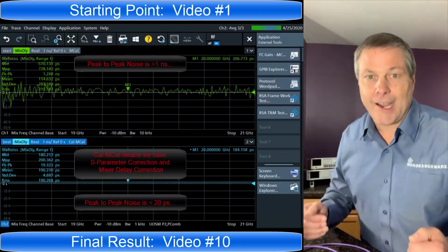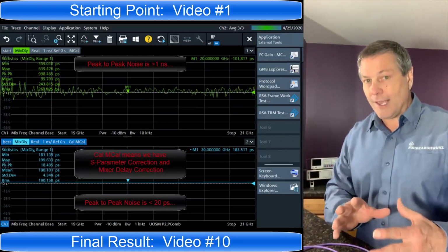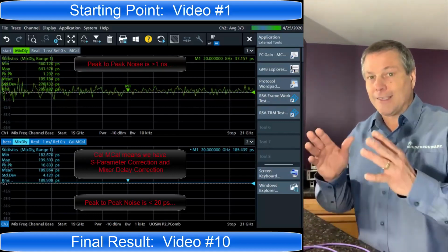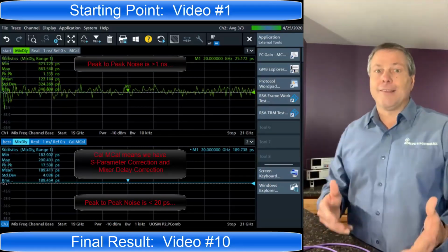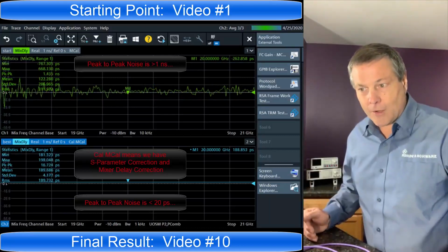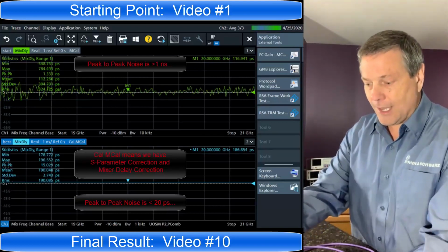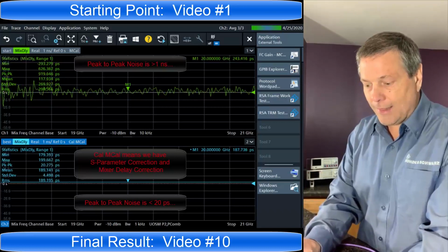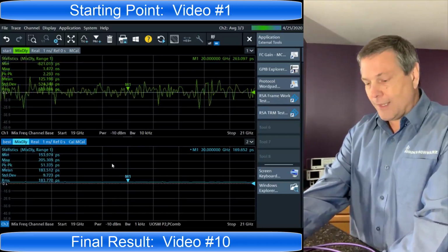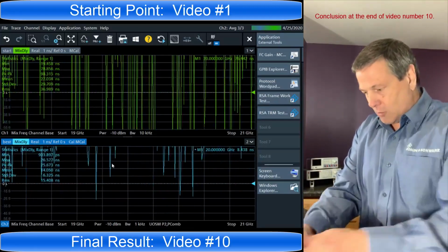This is the most exciting feature on my top 10 list, and it's the feature I covered in video number 10. So I'm not going to go through it again right here. You can go back and look at that video, but this is definitely something worth looking at. This is the best thing we have right now for making our group delay measurements as accurate as possible. So I've calibrated the two channels. Next, I need to connect to the device under test, and I can see directly the difference from when I started in video number 1 to the conclusion at the end of video number 10 with respect to how accurate and how clean my measurement is.